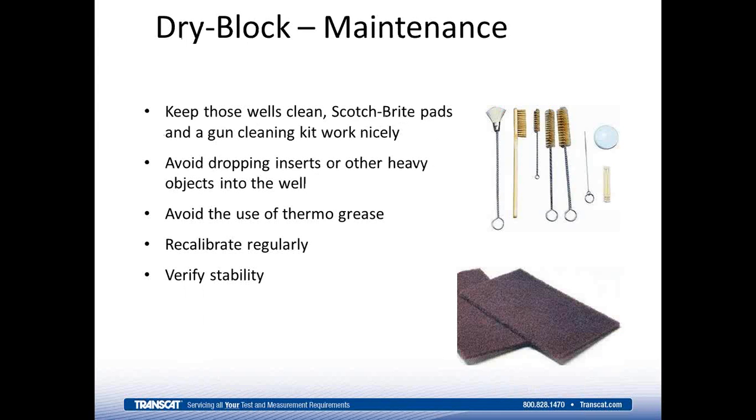We want to make sure we maintain the dry block calibrator properly. You want to keep the wells clean, keep the inserts clean. Scotch-Brite pads and a gun cleaning kit are what we typically use and recommend. You want to try to keep debris out of there, keep scaling and oxidation off the inserts as they are coming in and out of the instrument well. We want to try to avoid dropping inserts or other heavy things in the dry well. That can disturb the control sensor.